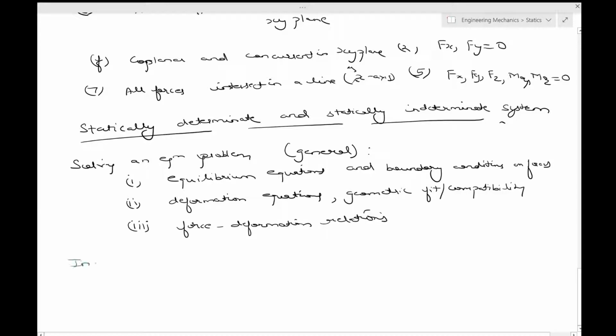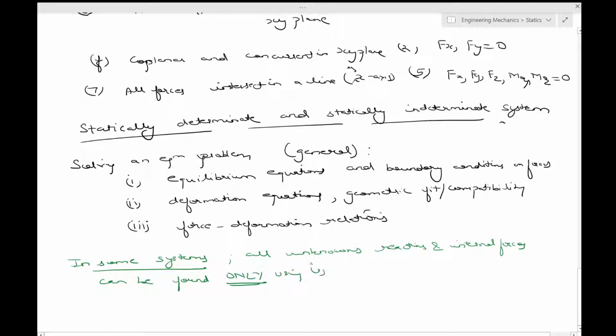In some systems, all unknown reactions and internal forces can be found using only the equations of equilibrium, without taking into account any deformation. So this is called statically determinate.